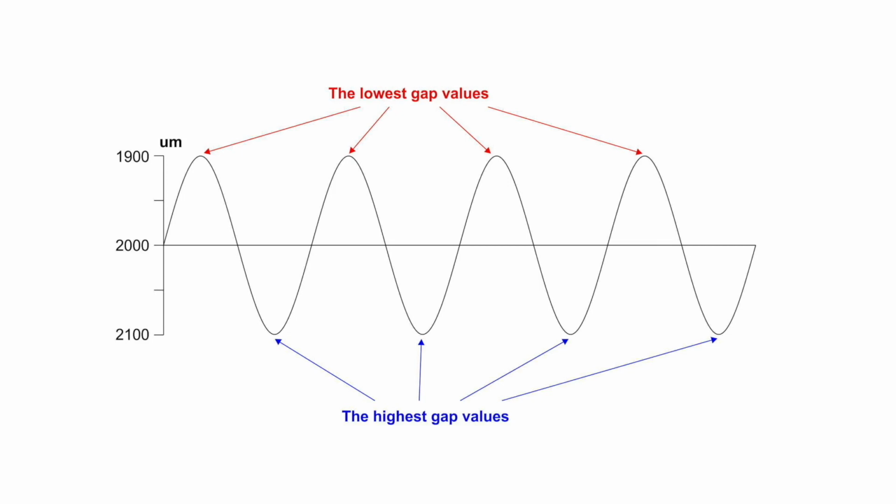But it's confusing. Usual understanding for measurement of anything is that the higher output voltage from the sensor means higher physical value. For example, higher voltage means higher temperature, higher pressure, and so on. But we can simply fix it on our analyzers. We only need to set correct values of sensitivity and offset. We need to set negative values for them.